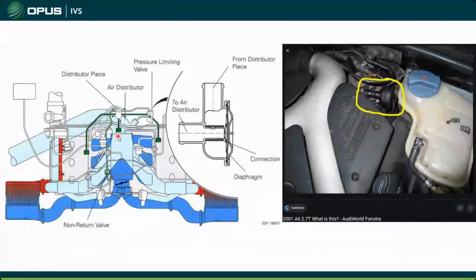This is one of the first times when they decided that, okay, when we're in normally aspirated mode, we're going to vent right into the manifold. When we are in boost mode, we're going to vent before the turbo, where there is vacuum. Basically, they want to vent wherever the vacuum is occurring, right? If you have boost, you can't vent.